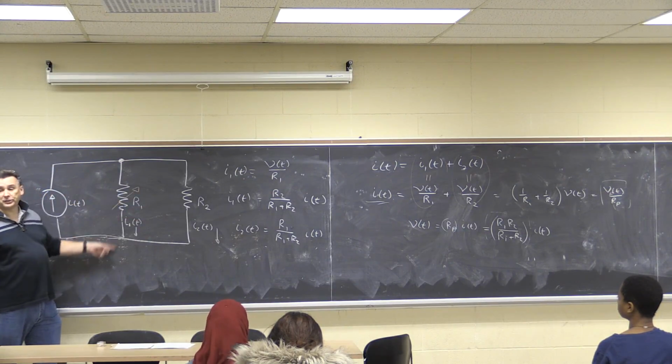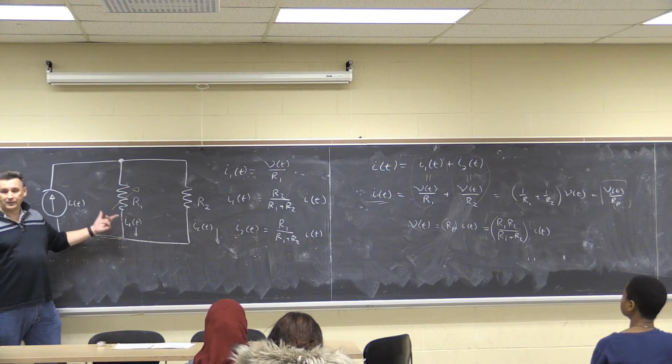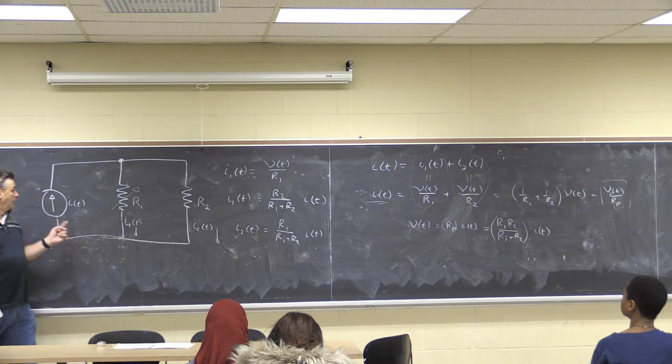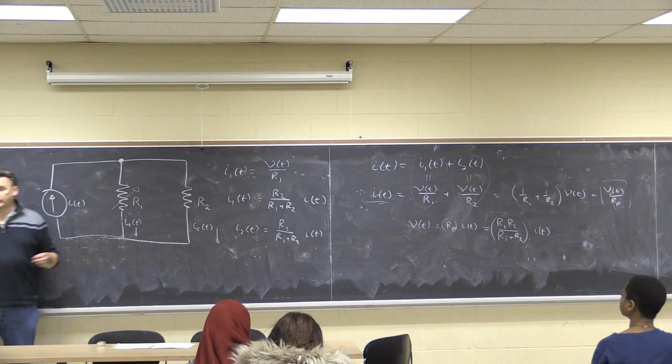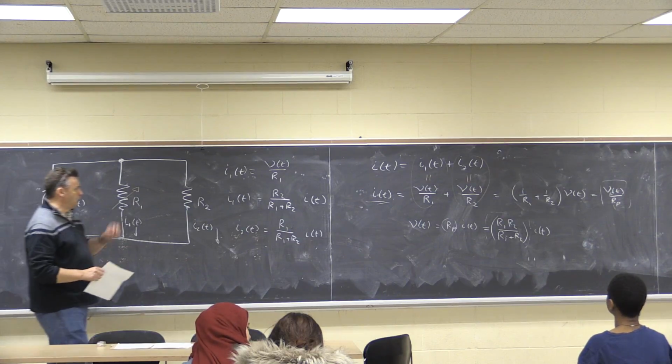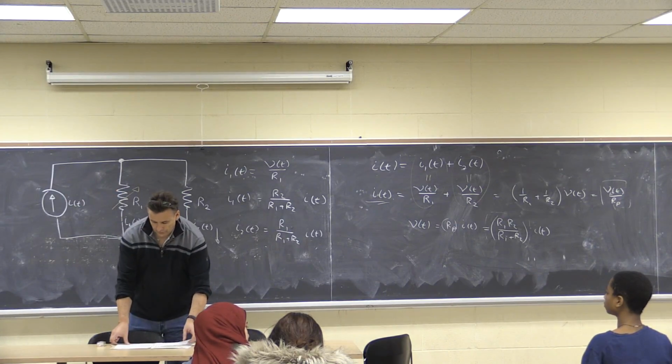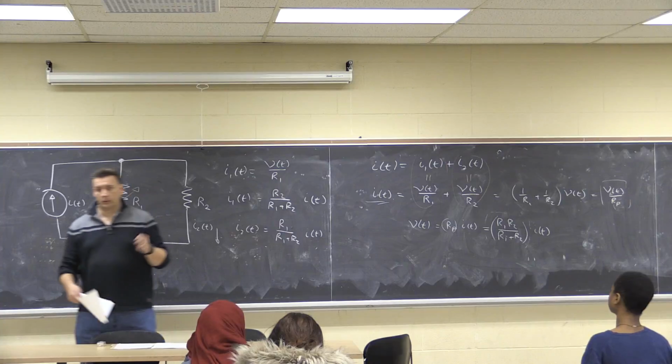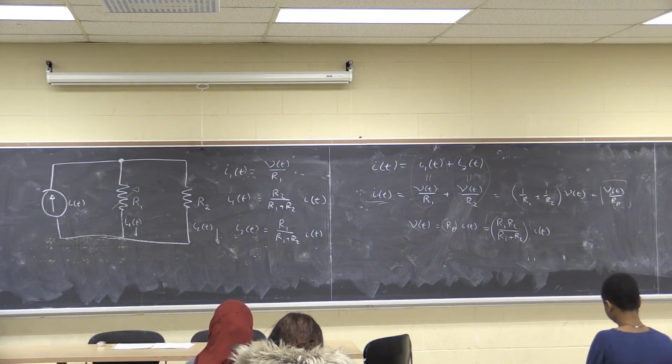If one of the resistances goes to 0, becomes what we call a short circuit, all the current flows through the short circuit. And again, those two equations confirm that. So these two rules, current division and voltage division, are useful when you're looking at combinations of series and parallel resistors, because they'll help you simplify the following circuits.